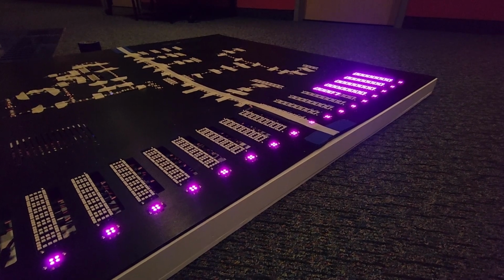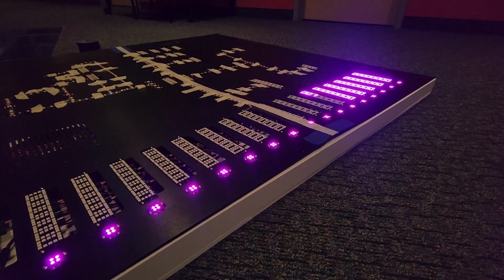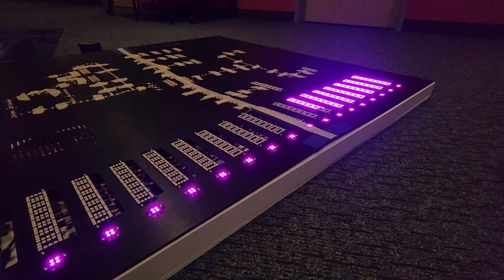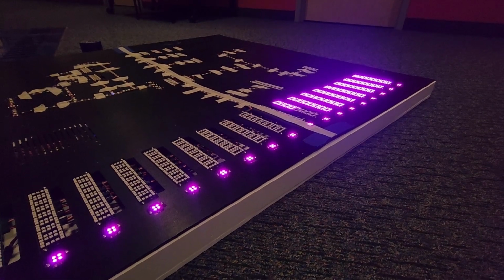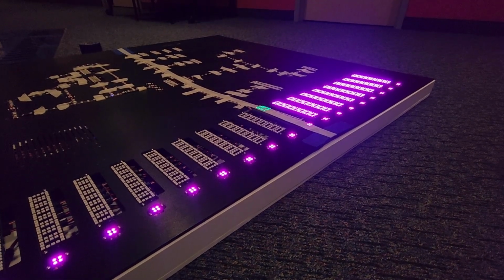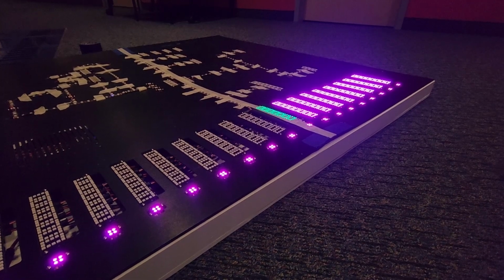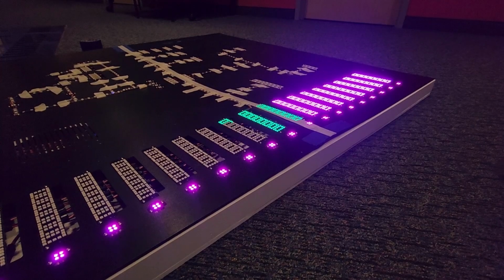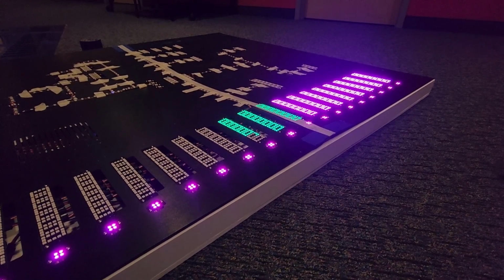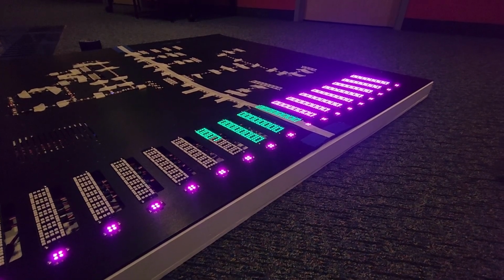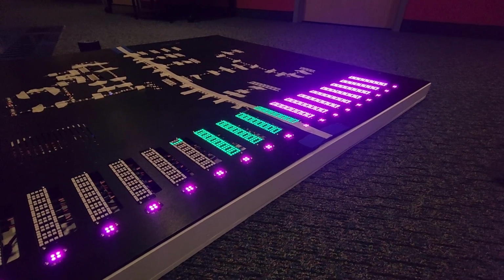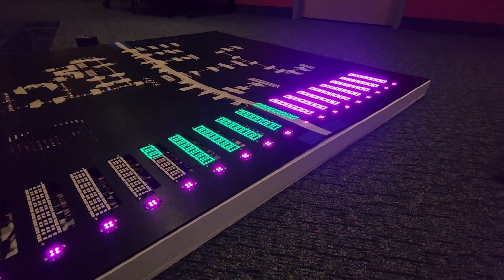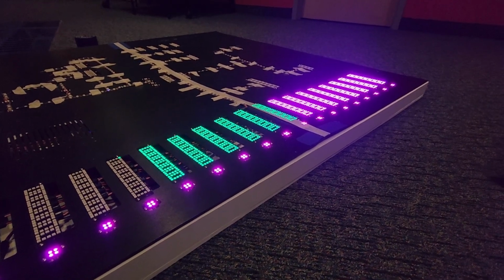Our final solution utilizes an ESP32 that can be controlled and configured both over UART as well as wireless Bluetooth to configure custom-made LED displays and LED strips made from the WS2813B LED variant. The overall system was designed in a modular fashion and includes several features such as backup data lines on the LED control circuitry, cooling circuitry including a thermistor and several fan headers, as well as the inclusion of the readily available and standardized IEC C14 plug with an integral power switch which matches with an IEC C13 cable.